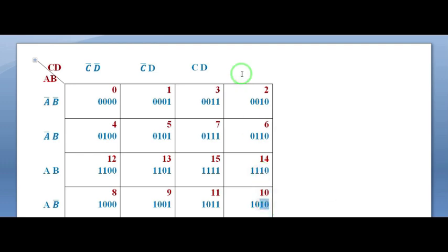All the cells of column 4, which are distributed into 4 rows, have 1 and 0. Here logic 1 is used to represent the C variable, while 0 is representing the complement of the other variable D. That means the fourth one is C D bar.